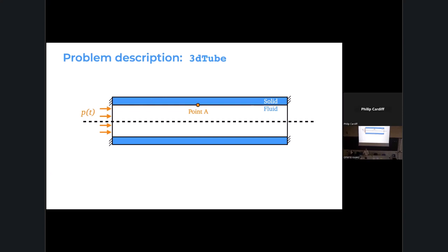So you have a deformable pipe, and typically an assumed incompressible fluid. You have zero pressure at the outlet of the fluid, and then you apply a kind of step function of pressure. You suddenly apply a high pressure, hold it for a time, and then drop it. Like a step pressure. If it was just rigid walls, the pressure wave would travel infinitely fast in an incompressible fluid, so you don't see a wave of pressure traveling. But with a deformable, flexible wall there's a finite wave speed in a compressible solid, and that actually creates a finite wave traveling in the fluid, which is kind of interesting.